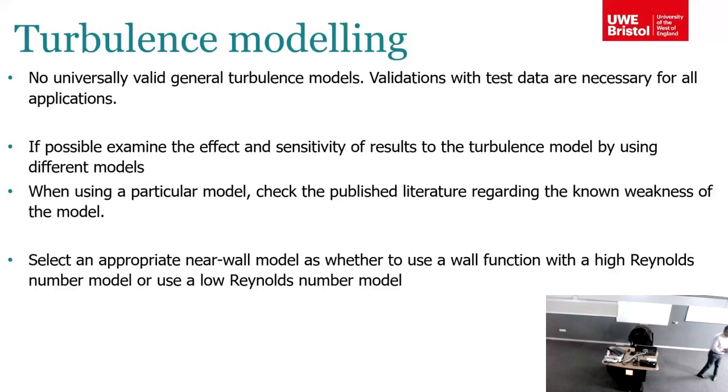So when you use turbulence models, there is no universally valid model. So you need to use a model depending on your experience and the problem in concern. If possible, if you have time, you need to check the sensitivity of the solution to the turbulence model as well.